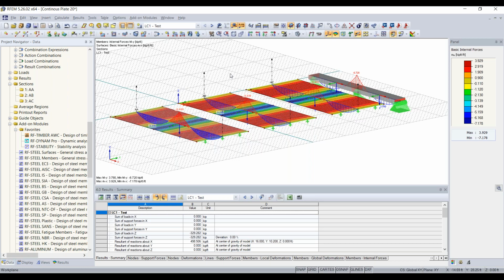Of course, you can draw a surface with the relevant materials and properties for a semi-rigid diaphragm, but it's not an actual diaphragm element in the program. It's really just a surface or a plate element, and we don't provide the analysis with chords and collectors and things like that at this point. So it's just purely FEA. Hopefully that answers that question too. Okay, I think that's it for now.